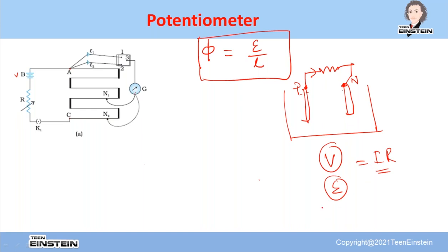Okay, they have a relationship like this. V is actually this minus I into R. This R is the internal resistance of a cell, because when current I is passing through the external circuit, suppose this is capital R, in the electrolyte the same current is also flowing in the opposite direction. Same current is flowing, and in the electrolyte, suppose there is some resistance, so there will be a drop in that.